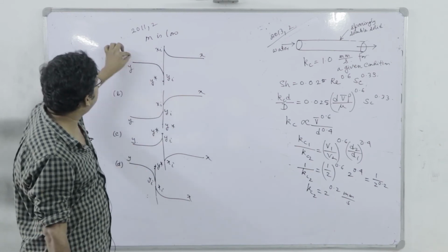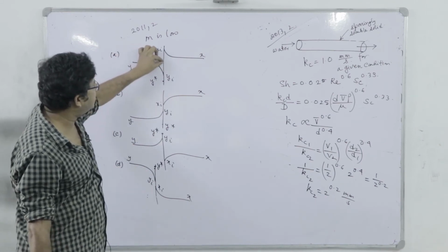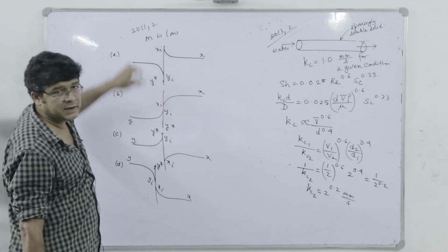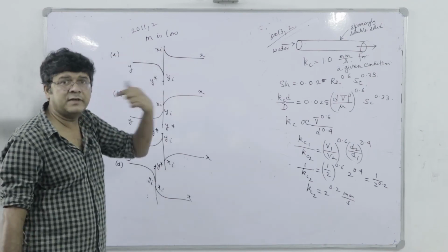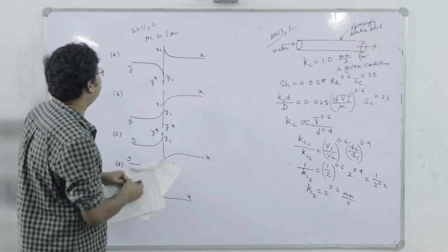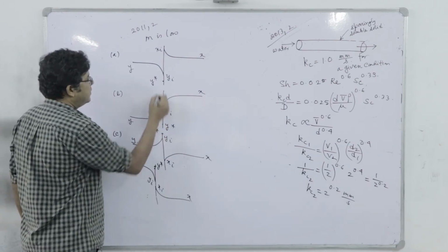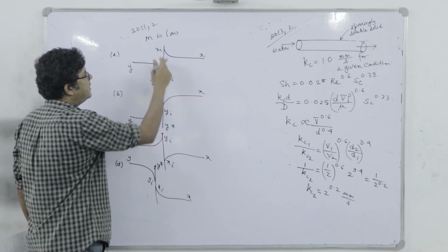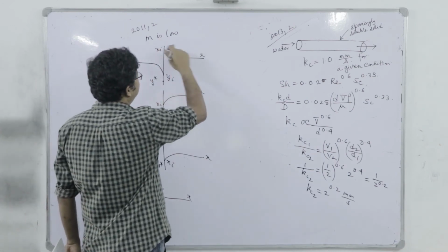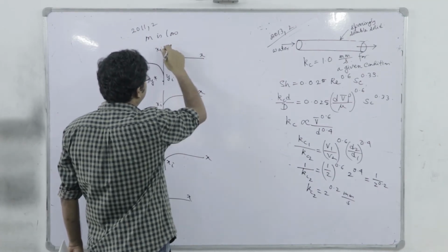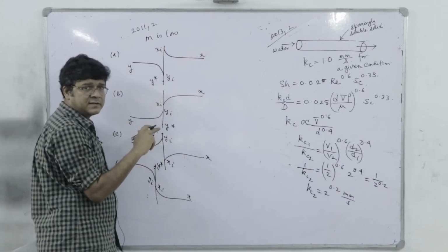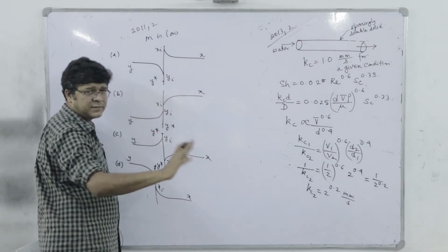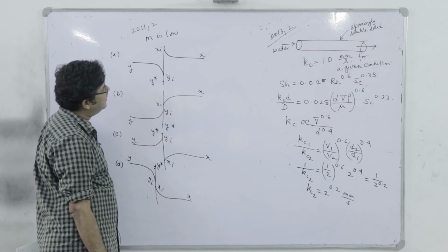So if I have to maintain the same flux here and here, we need a higher driving force here compared to the bulk region. Driving force is the change of concentration. So concentration must fall close to the interface on the gas side and must again fall towards the bulk in the liquid side, if it is a process of mass transfer from the gas to the liquid.